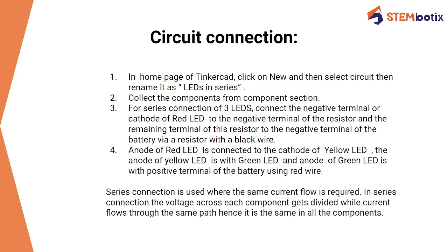Now your circuit is ready to simulate. Click on the start simulation button, and you'll see your three LEDs are turned on. This series connection is used where the same current flow is required. In series connection, the voltage across each component gets divided, while the current flows through the same path, hence it is the same in all components.